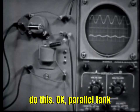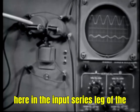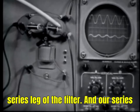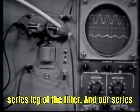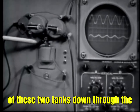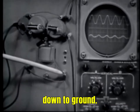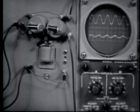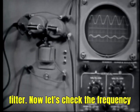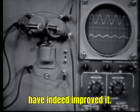Now let's do this. Okay, parallel tank here in the input series leg of the filter and a parallel tank in the output series leg of the filter. And our series tank now is connected from the junction of these 2 tanks down through the capacitor, the inductor in series, and down to ground. So we have a T section band reject filter. Now let's check the frequency response of this circuit and see if we have indeed improved it.